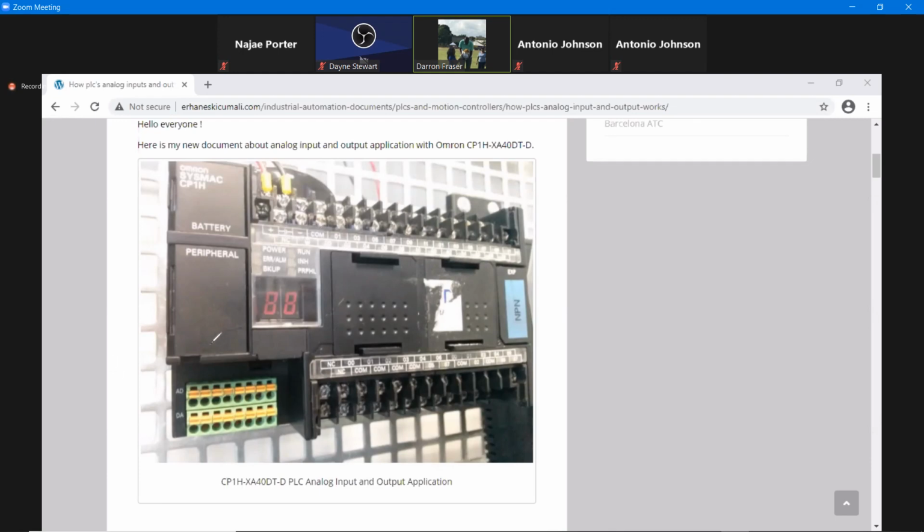All right. So last time we were saying that when you have the PLC, the parts that we have here with the 0.1 and 0.2 are digital outputs, meaning that you can turn on and off. And over on this side here, we have our inputs, binary inputs, so that we connect our sensors, on and off sensors, to our input side over this side here.